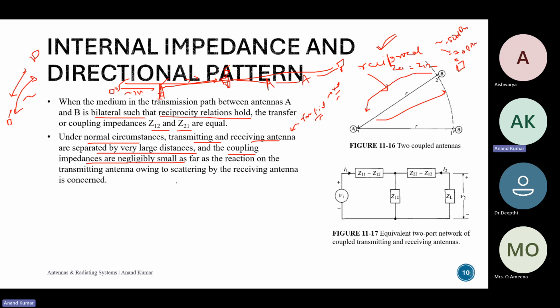The amount transmitted is usually around 0 dBm to 10 dBm, maybe. I think that's the maximum, but do check. The difference between the transmitted and the received signal strength is almost around 60 to 70 dB.